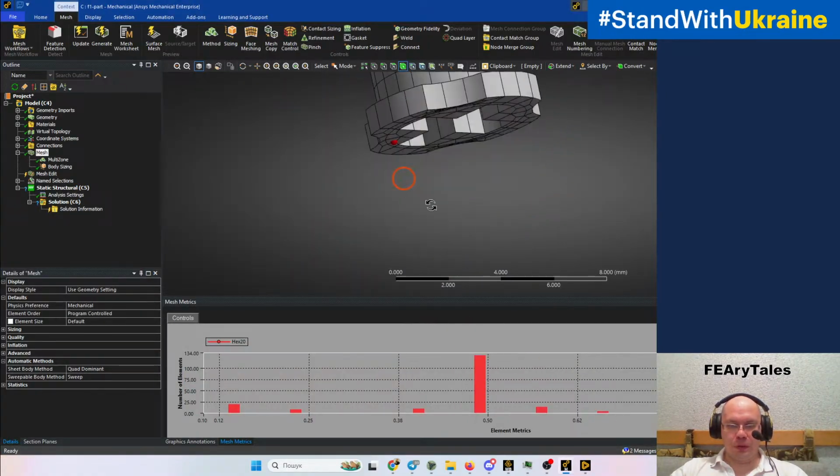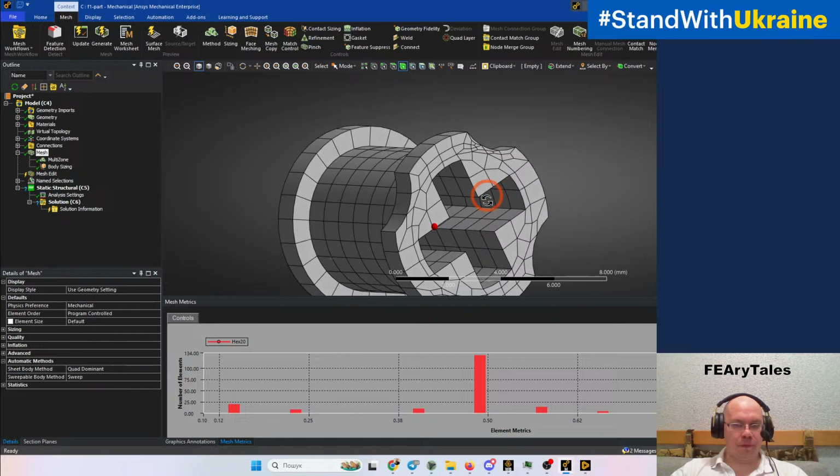So when I teach my students, I recommend they mesh the split geometry with a mesh preference of 3 or 4 elements per edge.